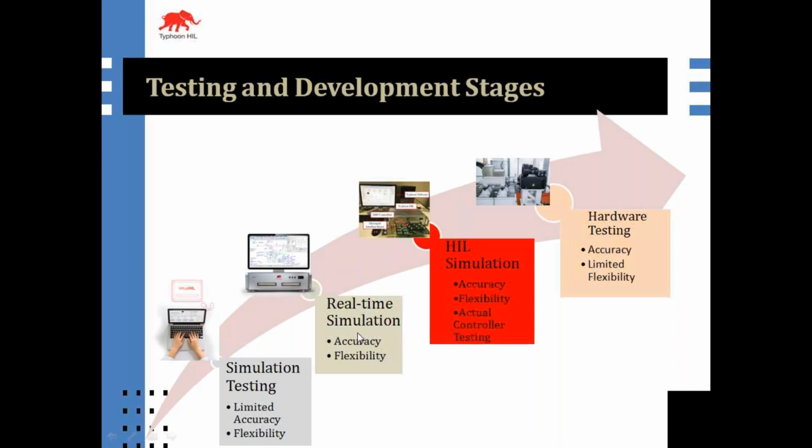But when we go for real-time simulation, that refers to a computer model of a physical system that can execute at the same rate as the actual wall clock time. So now the simulation is very similar to virtual. The only difference is that after compilation, both plant and controller go to the process through a specific device called a real-time simulator.